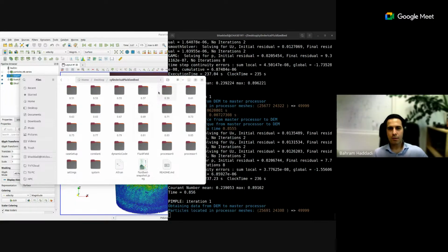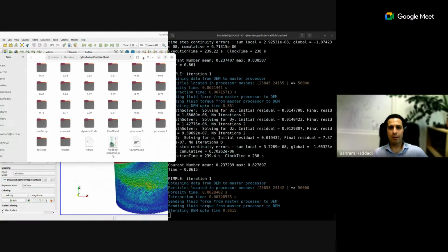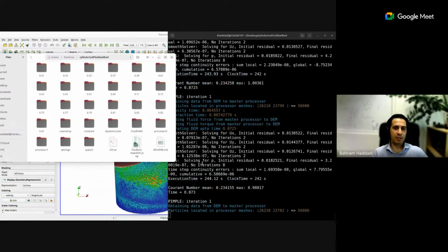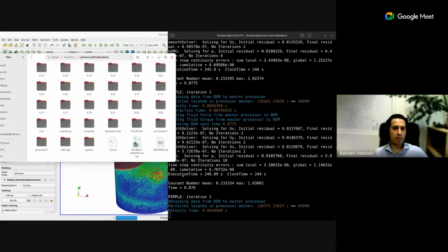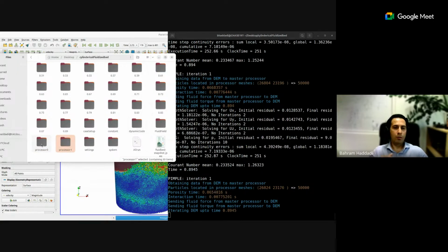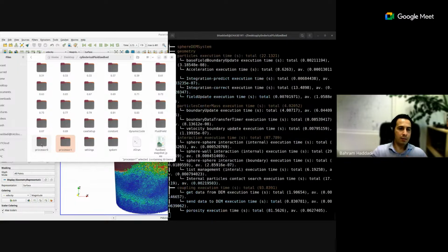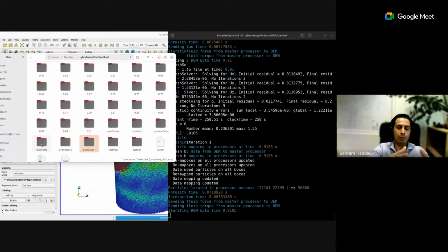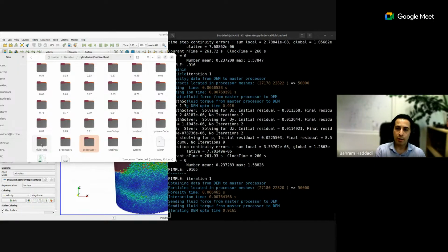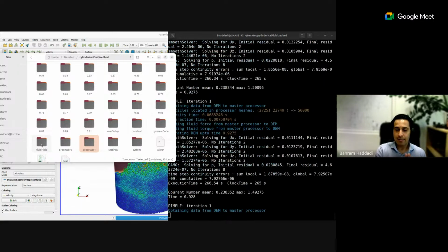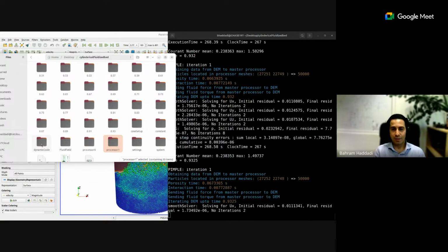Yes, as the closing word, I have been already running the simulation in parallel mode also for the CFD side. As you can see, it's much faster, just in this short time that we were talking it reached almost 1 second of simulation. And now we have the processor 0 and processor 1 folders in there. To handle this, we simply do a reconstruct, which puts the mesh and all the simulations together and puts it back to the simulation root folder. But for more information there, stay with us with our OpenFOAM lecture series.